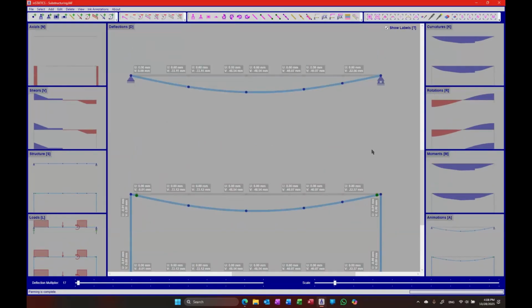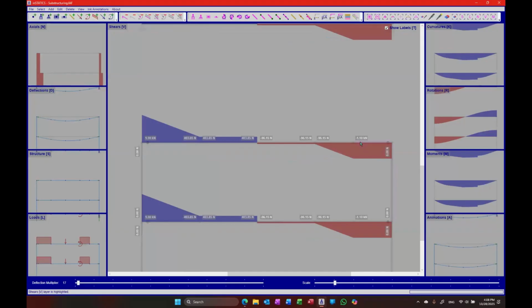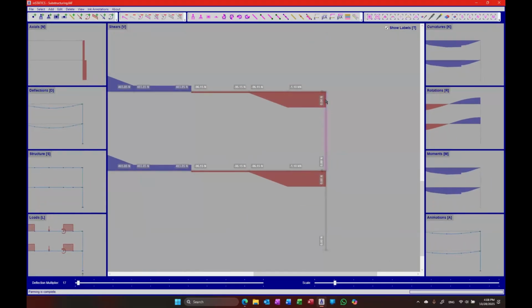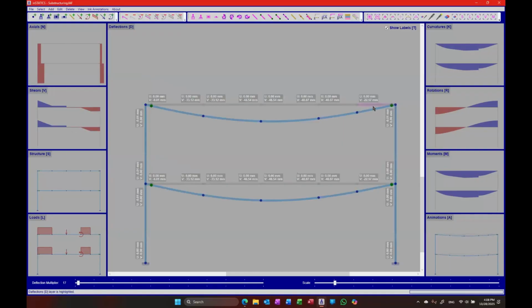So in those cases, when this much shear, let's say in this case 1.1 kilonewton, is applied on the column, you have to figure out how much of a deformation is going to come here, and then how much of a deformation is going to come to this point, and then basically find out how much you need to add to the deformation of this element at each node.